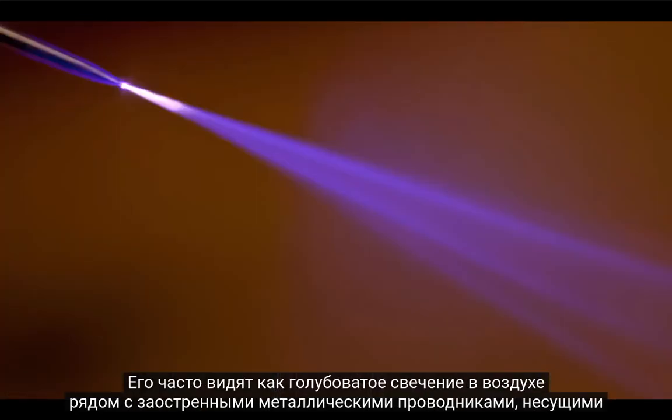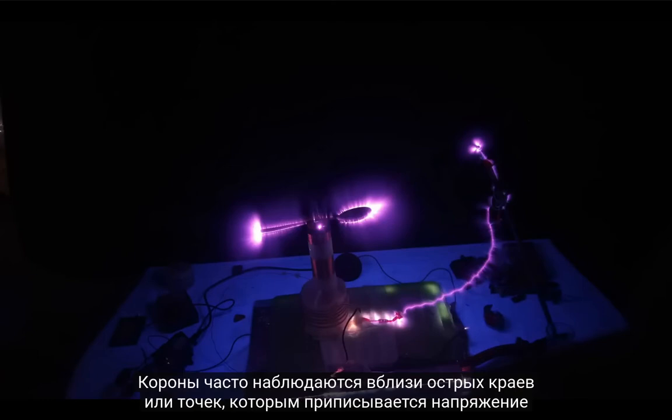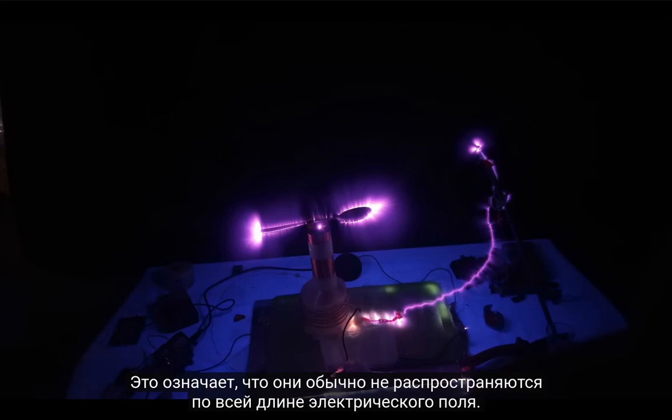It is often seen as a bluish glow in the air adjacent to pointed metal conductors carrying high voltages and emits light by the same mechanism as a gas discharge lamp. Corona are often observed near sharp edges or points that have a voltage attributed to them. This means that they don't normally propagate over the entire electric field.